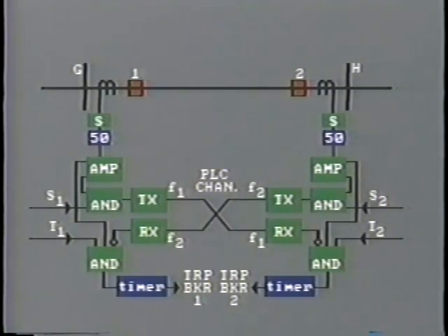As before, a special filter circuit is connected across all 3 CTs. If a phase fault or ground fault is present, this filter will produce a single phase voltage at its output terminals. The polarity of this voltage depends upon the direction of the current flow into or out of the power line. Actually, the voltage produced by the network circuit is not a sine wave, but a half-cycle square wave, like this. The transmitter is an on-off type, therefore a starting relay is required.